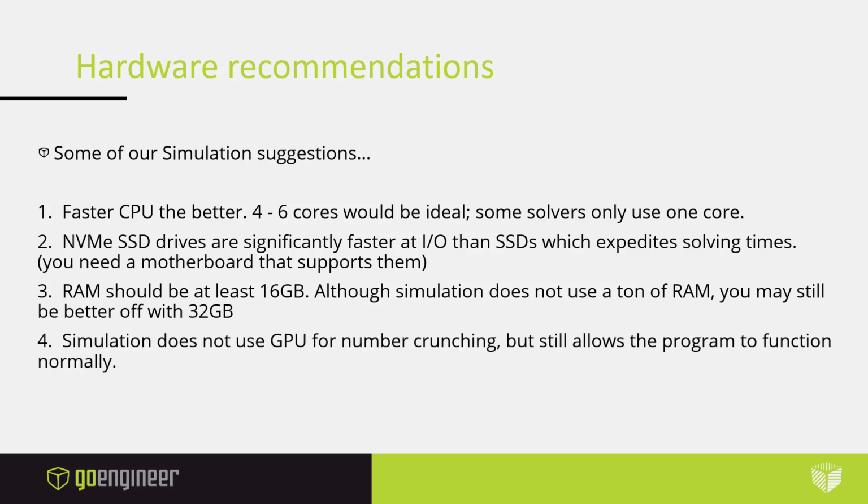Lastly, simulation doesn't use the GPU, but in order for the program to run correctly, if you have a simulation computer and you're only using it for simulation, you still want SolidWorks to run on that computer. So you want to have a certified GPU.